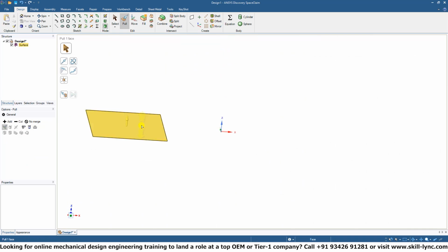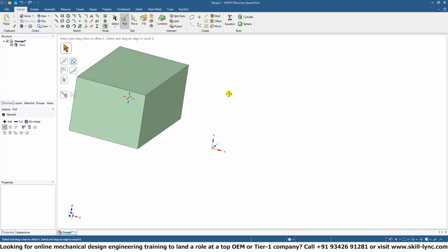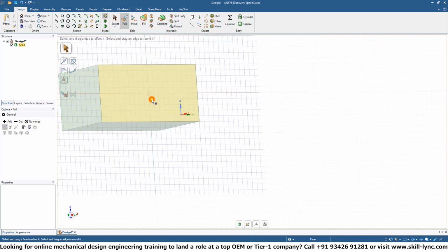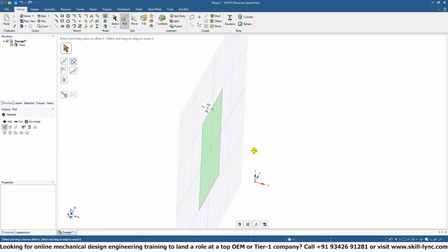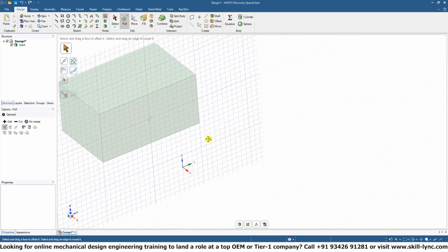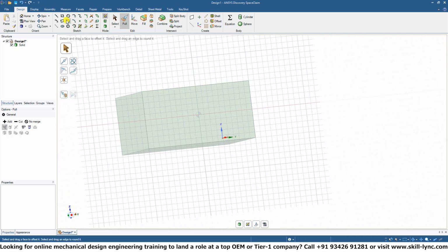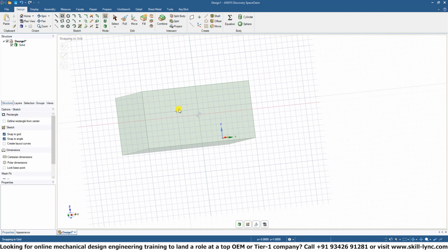You can extrude that up to your desired length. If you're happy with the head of the hammer, you can start working on the handle by selecting a plane, as we have previously covered and discussed, on the face of the head of the hammer, and simply moving the sketch plane around, we can define over here a position for our handle.